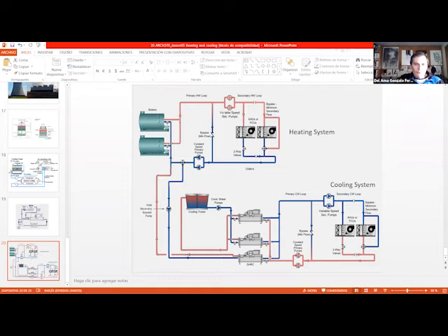So usually we have 2 things in parallel like this in these building systems. It makes the system much more complicated because we duplicate the devices, we duplicate boilers, chillers, and water pumps, but at least we have a backup. So if something is wrong with one of the devices, we can make sure that the building is not stopped.